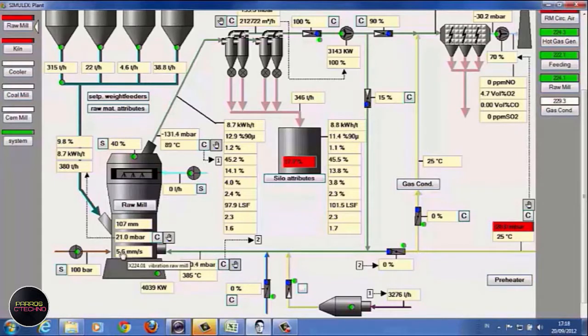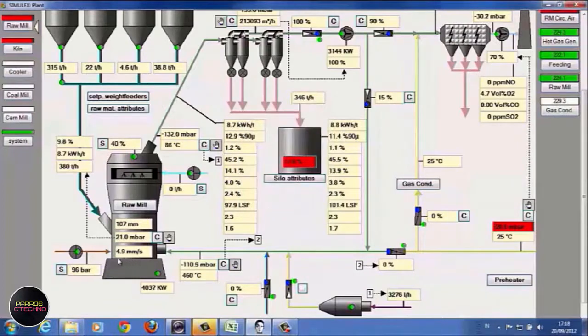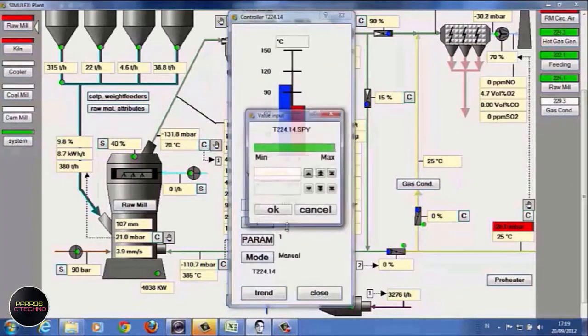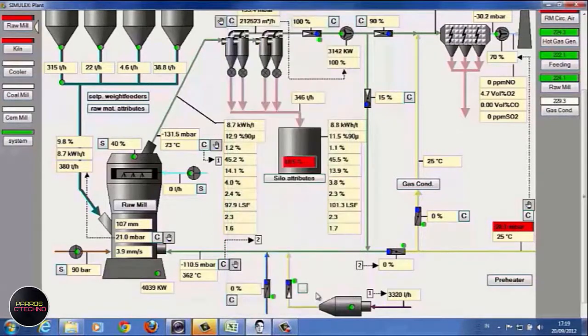Okay, the vibration still won't go down, let's lower the hydraulic pressure to just 90 bar, hopefully it can go down. Now it can go down. It can be seen that all the quality is close to good. Just because the outlet temperature can't go up, we try to add another 1% of the oil usage. Hopefully this can help to reduce the moisture content of raw meal products. Hopefully it can drop below 1%.